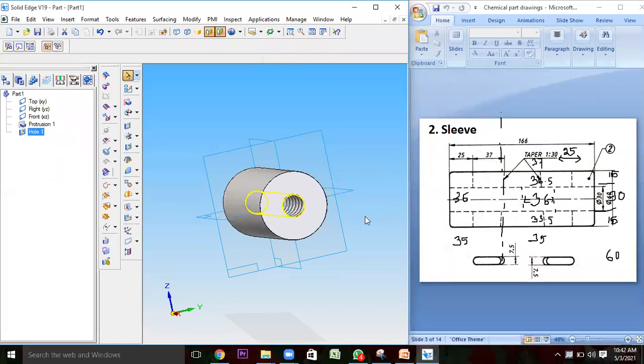If I use the 30 mm hole option, then I can directly go over here and by just clicking dynamic edit, I can change this. If I use the cutout option, what should be done? At that time the cutout option should be deleted, and then the hole option should be created once again. Instead of that, the dimensions can be changed if we have used the hole option. So whenever we have any circular cutout, preferably use this hole option. If you cannot use the hole option, then go for the cutout option.